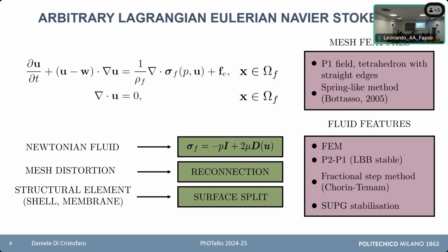And lastly, just because I'm from a mathematical background, I have some mathematical stuff. I'm using the finite elements method. The mesh is composed of tetrahedra that always have straight edges, and we are also solving with some stabilization to take into account a high Reynolds number.